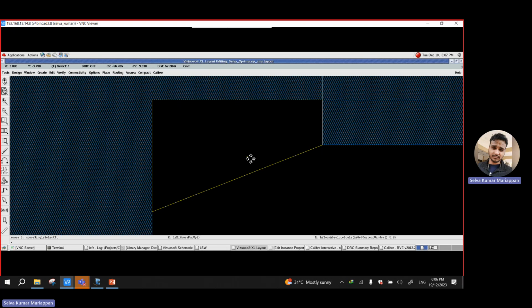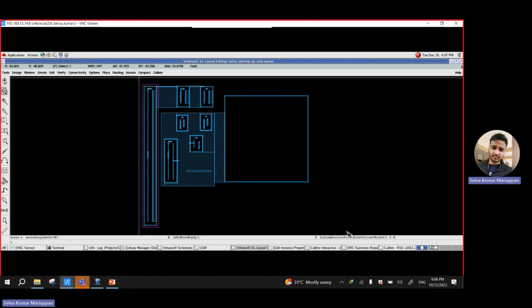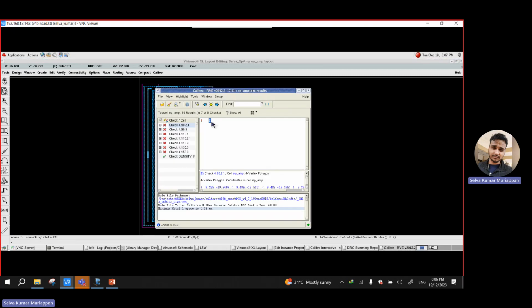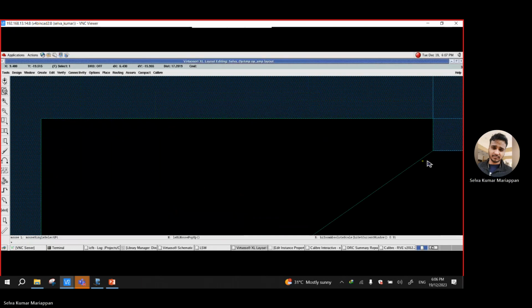So that's professional level. For you guys, just learn to draw first, okay? Because you must have this DRC check. So how do we solve this? We'll just put a rectangle there, like that, and then the DRC error will disappear. Let's look at another one. We have another one here, from here to here. So I just draw it again.